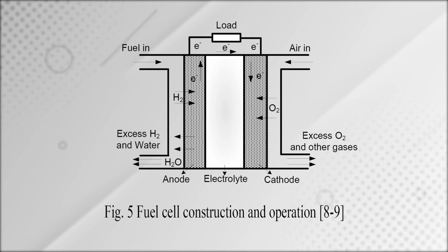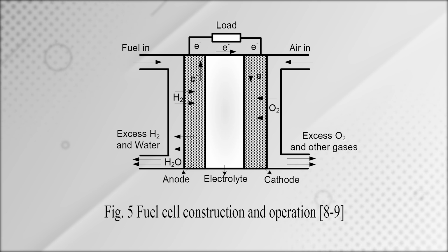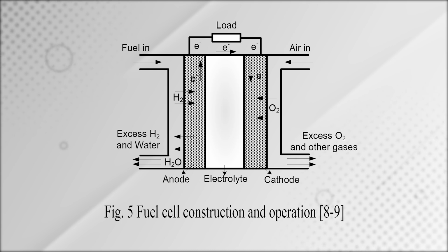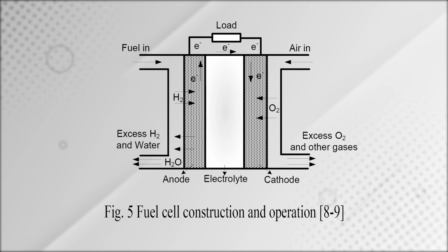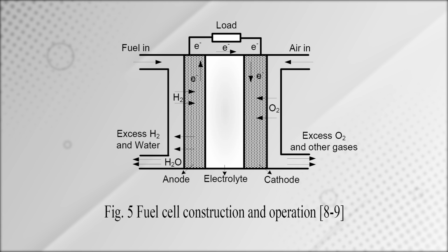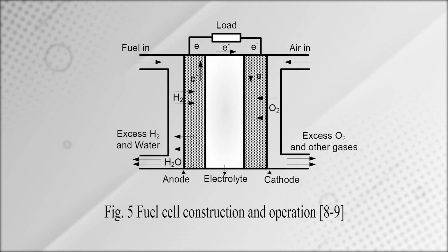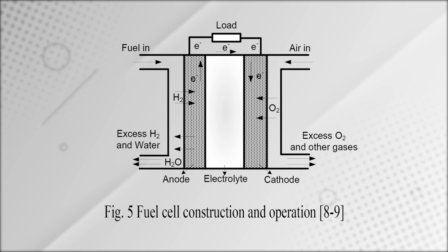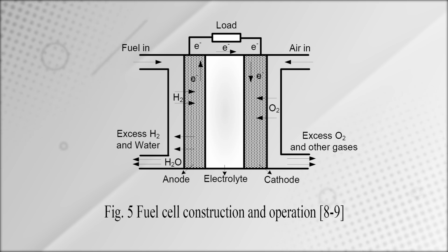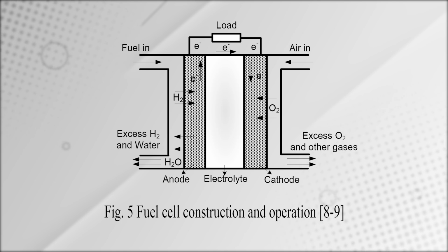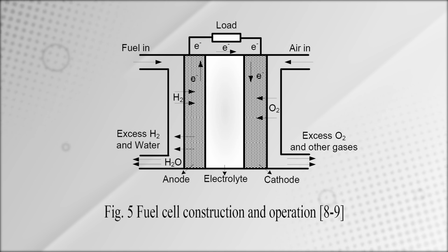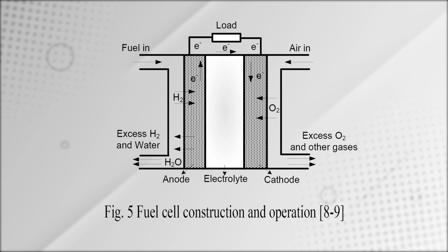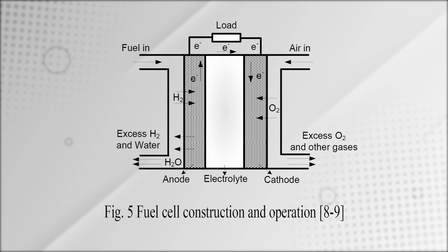While fuel cells have a specific energy comparable to gasoline, their specific power is lower, leading to poor starting performance in fuel cell vehicles. To address this, batteries or ultracapacitors are often used in tandem with the fuel cell to improve power density and starting performance. Thus, a fuel cell and ultracapacitor complement each other, providing an optimal energy storage and supply solution for automotive